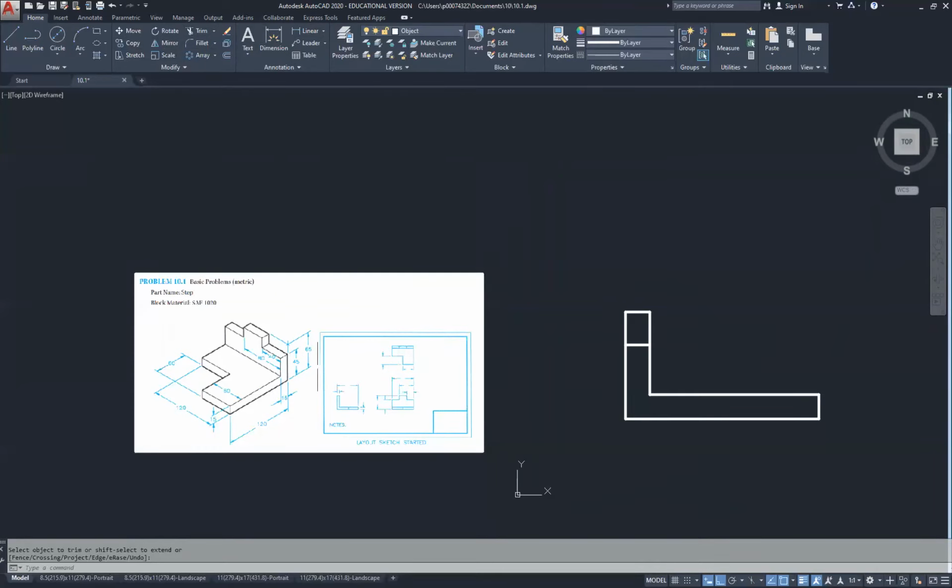This may be a little deceiving to some that we're looking at the right-hand side and drawing the left-hand side. The reason why we want to use the left-hand side over the right-hand side is to eliminate a hidden line that's here. So we'll be able to see this side with our solid lines, which will lead to better dimensioning and stuff like that.